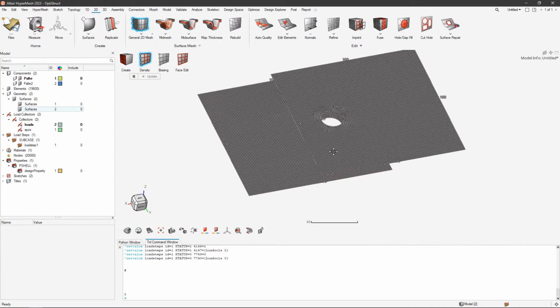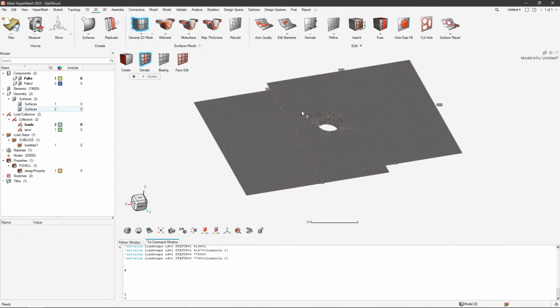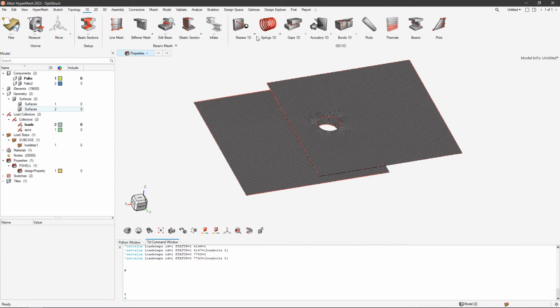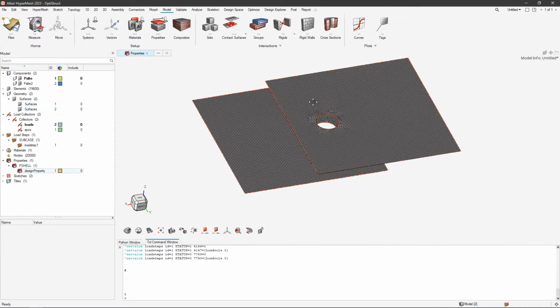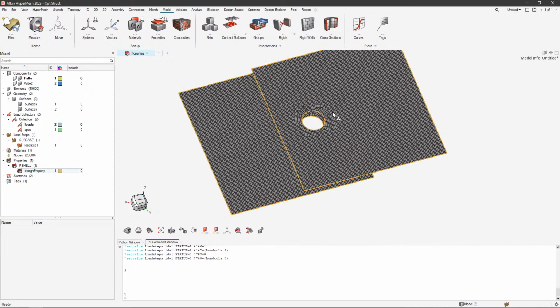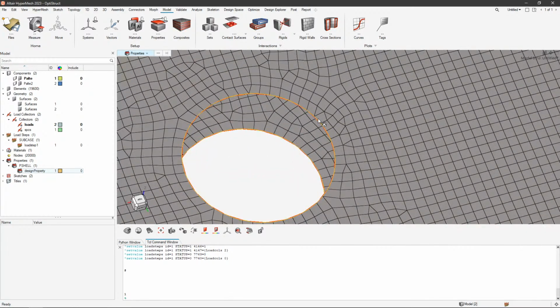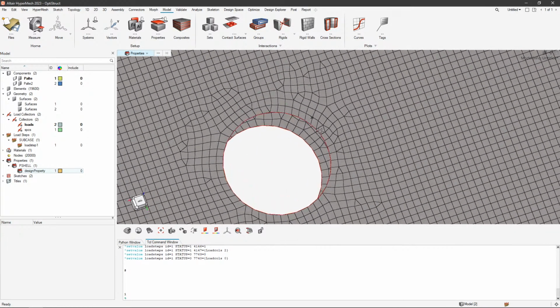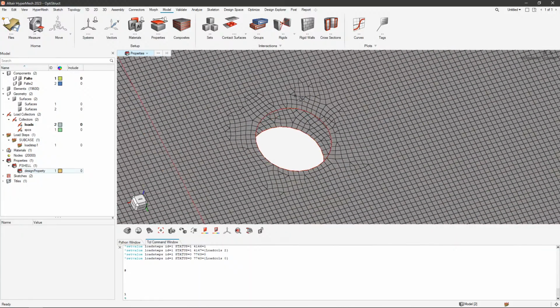Yeah, I will use a rigid just for simplification, not an RBE3. We could talk about the difference between RBE3 and RBE2 here, but I will just use an RBE2, a rigid. This means motion between the slave nodes is prevented. It makes it a little bit more stable too.